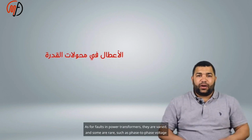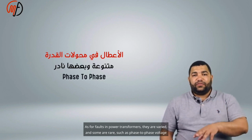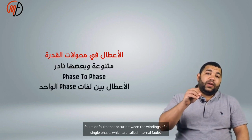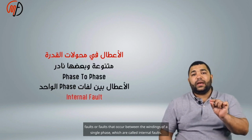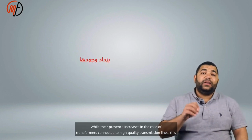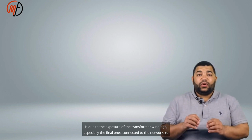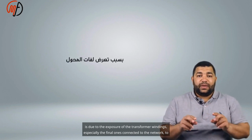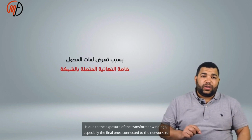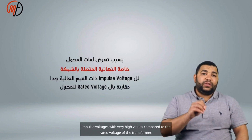As for faults in power transformers, they are varied, and some are rare, such as phase-to-phase voltage faults or faults that occur between the windings of a single phase, which are called internal faults. This type of fault is rare in transformers used in low voltage applications. While their presence increases in the case of transformers connected to high-voltage transmission lines, this is due to the exposure of the transformer windings, especially the final ones connected to the network, to impulse voltages with very high values compared to the rated voltage of the transformer.